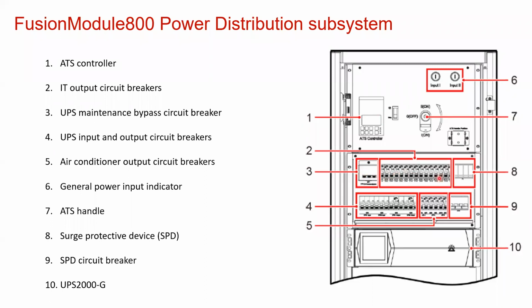In the distributed subsystem, each rack has the corresponding MCB, or corresponding electrical attachments, so you can control each rack's power. It is a safe circuit. It will not disturb the entire data center if a failure happens. Each MCB can trip if there is a short circuit within the rack. So this is the rack-level arrangement.